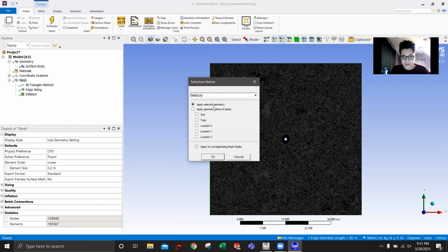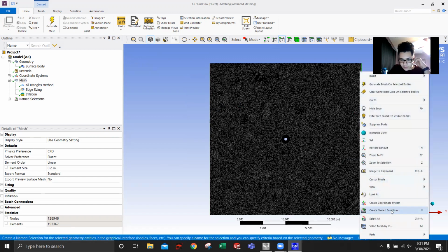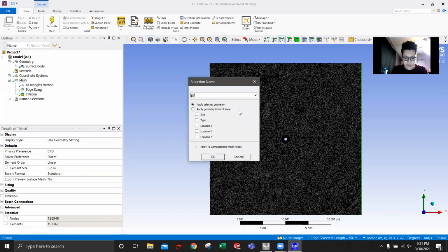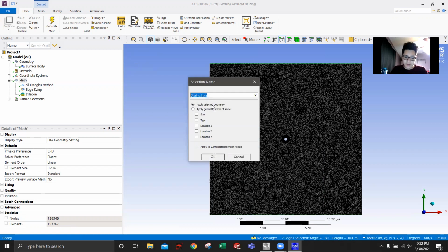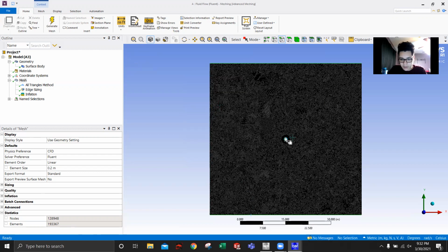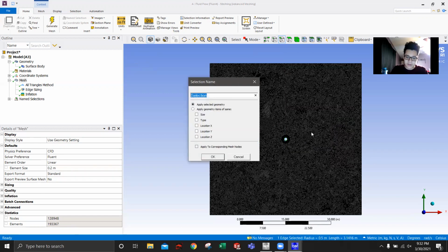So now what I'm doing, I'm just going to label our control area, control volume kind of thing. We're going to name the inlet, outlet, and then the walls themselves. That first one was the inlet, and then we're going to make the back end the outlet, and then the top and bottom we are going to call symmetry, but those are just the walls of the area itself. And then we're going to also name the middle. I'm going to just put cylinder.